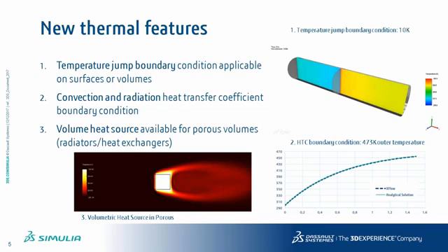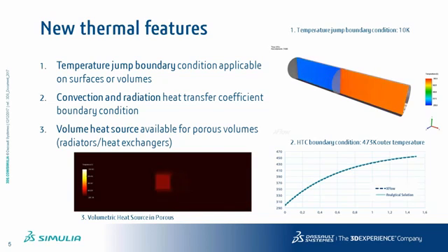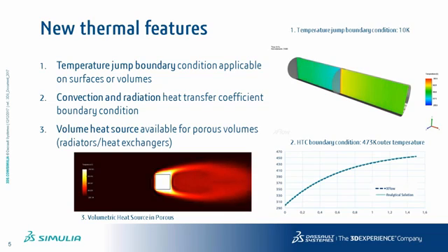So if you have, for example, a car where you have a radiator and it's a porous media, so you have a pressure drop of the flow going through, you can now in XFlow 2017X add a volumetric heat source. So as you can see, we are plotting temperature in the video, and we're going to have an increase in temperature on the entire volume of our porous media, and of course that will actually extend on the fluid side. Okay, so in this case we have a velocity inlet from the left-hand side sweeping through the domain, and you can see how the temperature is then diffused downstream of the porous media. So there is a good development for thermal analysis, for example, in the automotive industry.